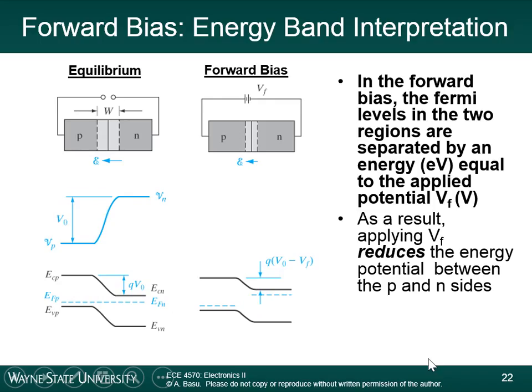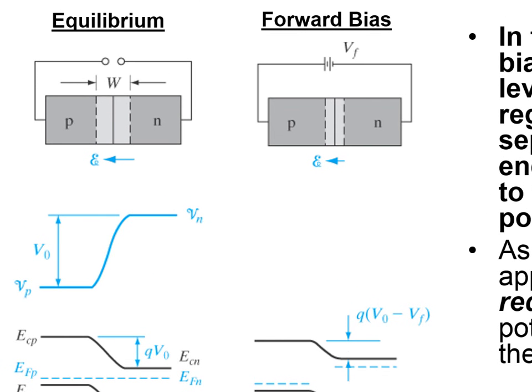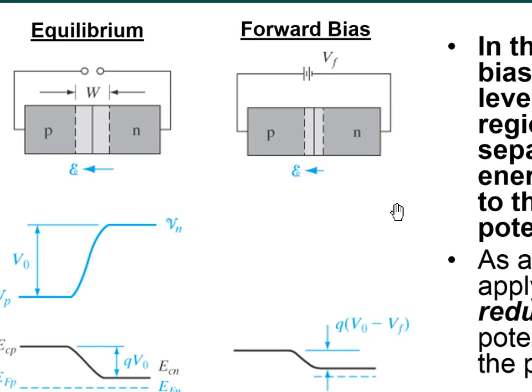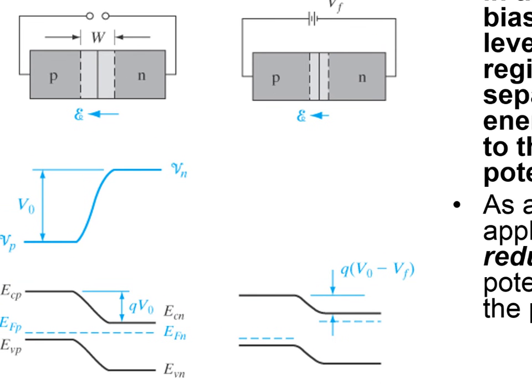Whichever side you place the forward voltage on, so for example, if we place a positive voltage on the P side of the junction, as is shown in this diagram, remember these battery diagrams, whichever side has the longer line, that's the positive potential, the smaller line is a lower potential. So this P side is at a higher voltage. This side has a lower Fermi level.